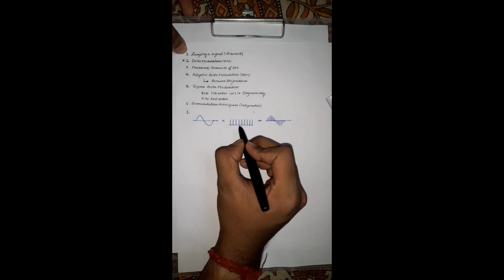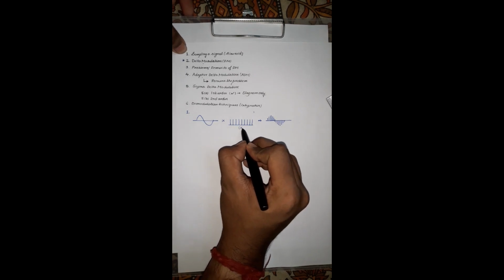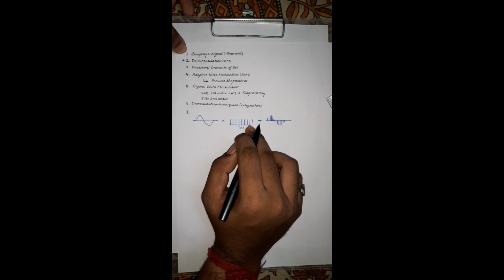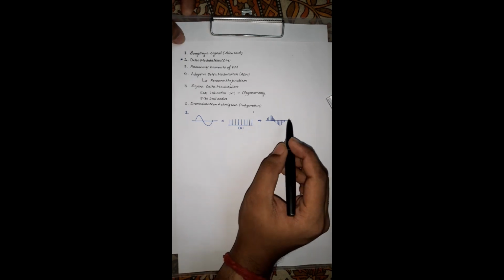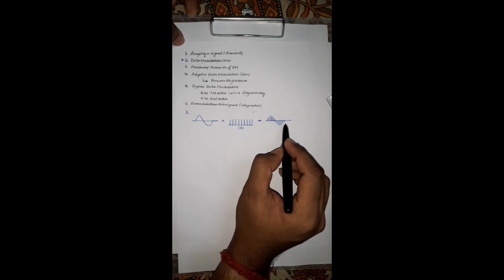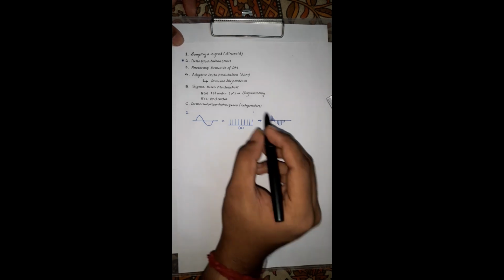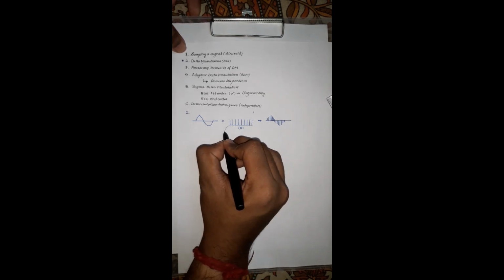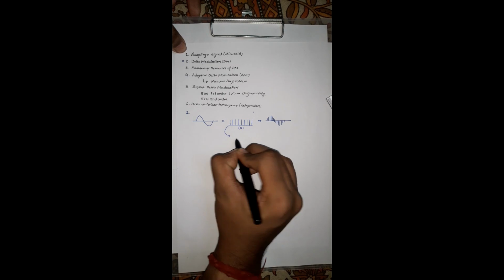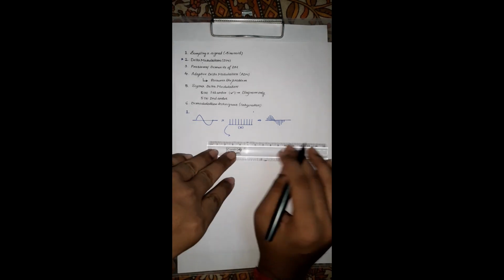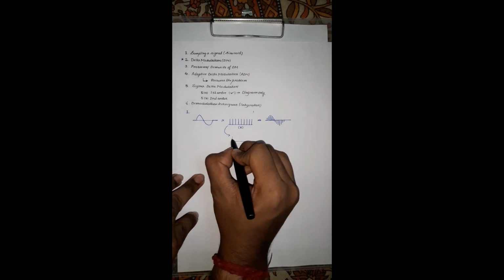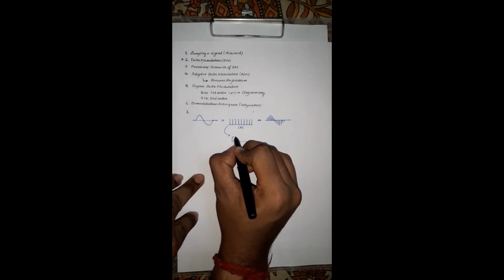That is, we cannot generate this impulse signal physically. As we cannot generate this impulse signal physically, the sampling that we are getting mathematically here, we cannot see it physically. So what we can generate in place of this impulse signal is a small number of pulses. We can generate the pulses of small widths.